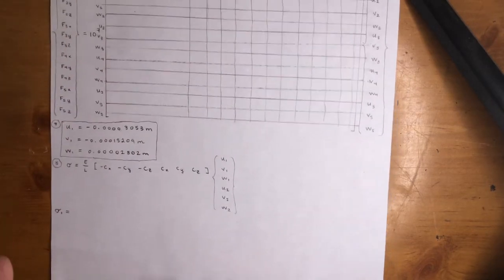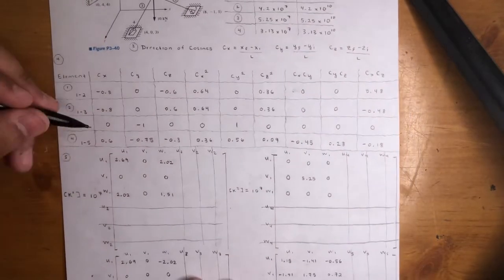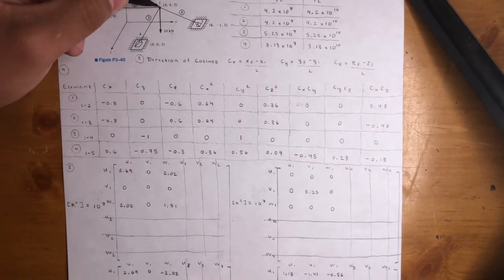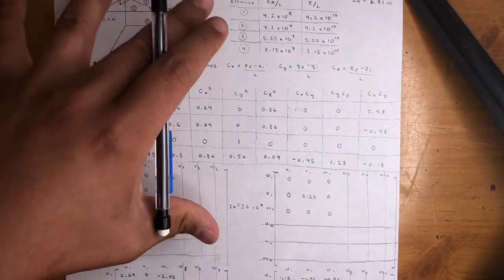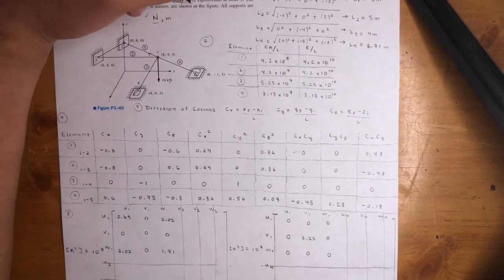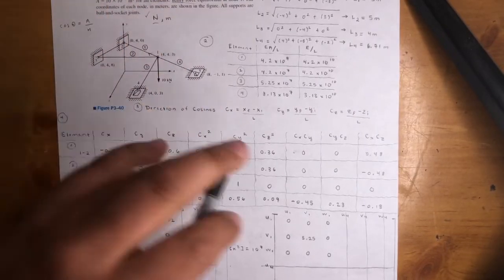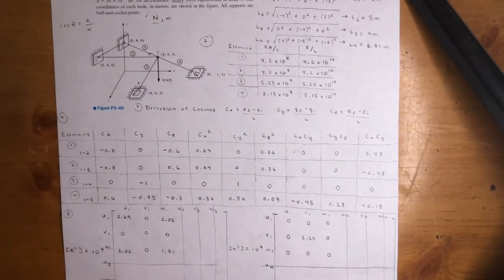So you'll get the same numbers in magnitude, but it will determine either compression or tension depending on the direction you chose. That's why it's really important that you do it a specific way, okay? It's real easy. It's not that hard, right? If you're going in the direction from 1 to 2, now you're going to do 2 minus 1. Just be consistent. You'll be all right. This logic doesn't apply when we verify forces, but I'll get there. Relax. This is only for the stiffness matrix up to the stress values.